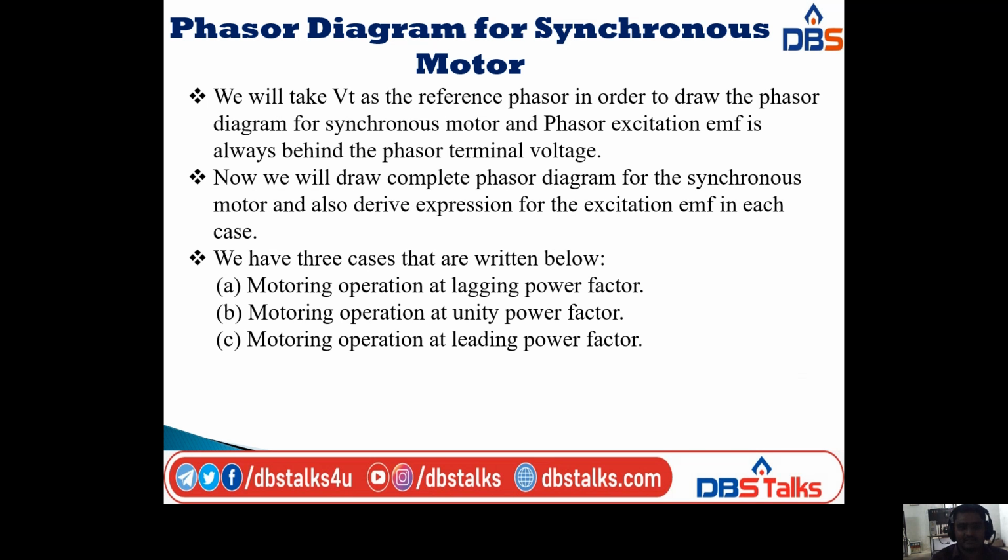To draw the phasor diagram for the synchronous motor, first we will take the terminal voltage as the reference phasor. And the phasor excitation EMF, that is EB, is always behind the phasor terminal voltage.